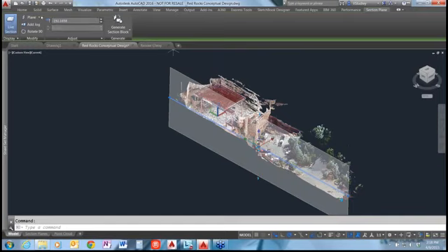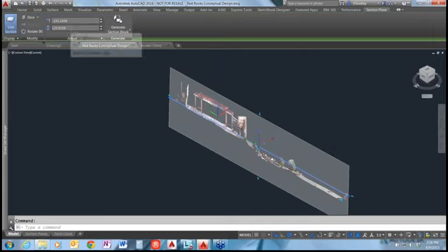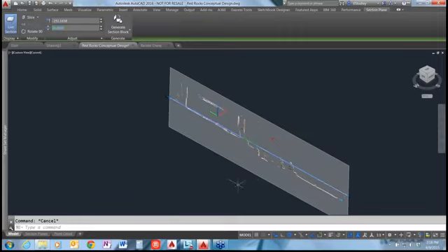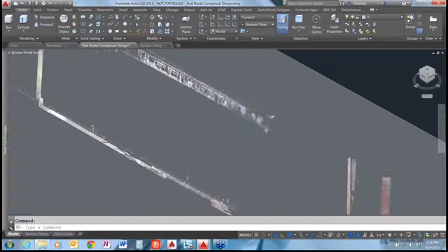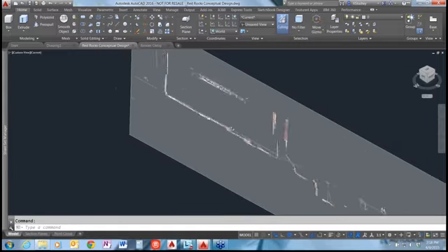And I'm going to switch this to a slice. And I'm going to set it at a very thin slice, so let's say maybe 20, and that'll reduce this down. And you can see, once it takes, when we zoom in, it's just got that very thin slice of the model taken out.